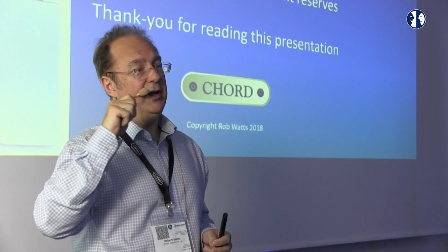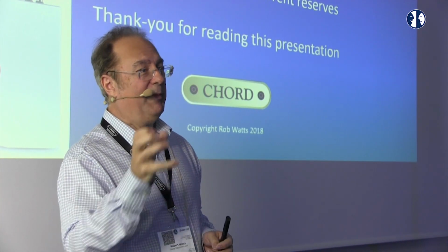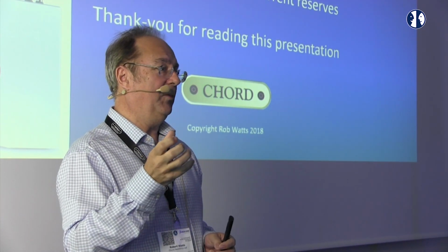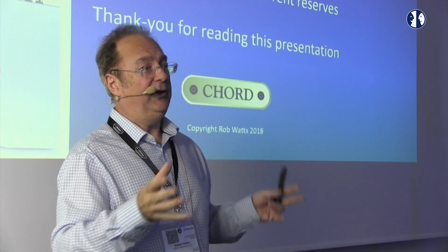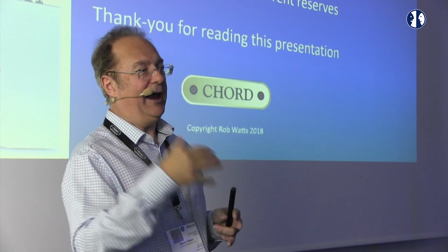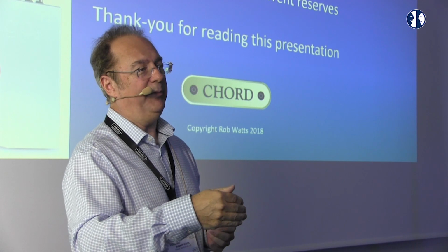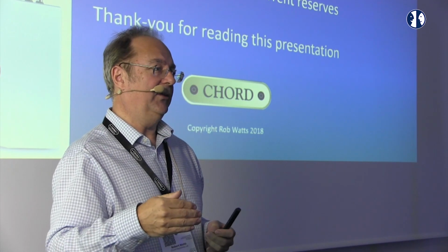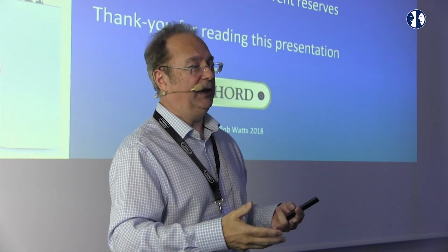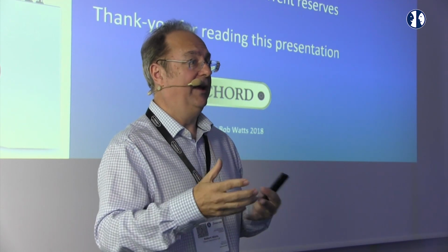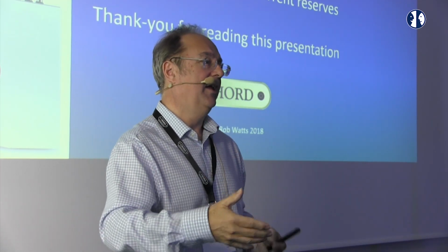If you play it through a 1990s A to D converter, it manages to capture that transient information more accurately. And it's because they tended to use analog filters that had very, very good stop band performance and no aliasing issues, rather than using modern day delta sigma and using that to create half band filters that create lots of aliasing.